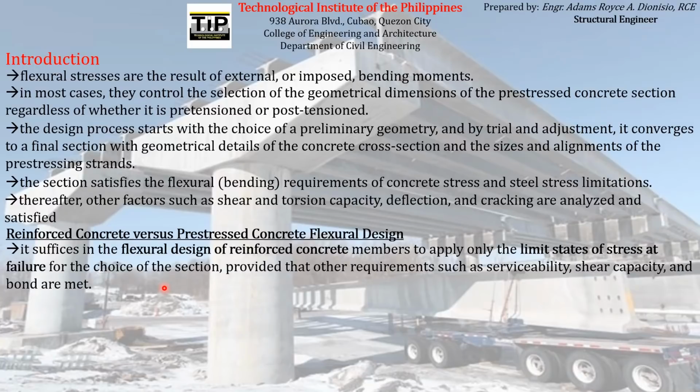So actually, when we say failure, we usually have a basis for us to say that a material or a member already failed. For the case of reinforced concrete, in terms of the design of reinforced concrete, we usually say that the design already failed if the steel reinforcements already yielded, as well as the corresponding concrete component.